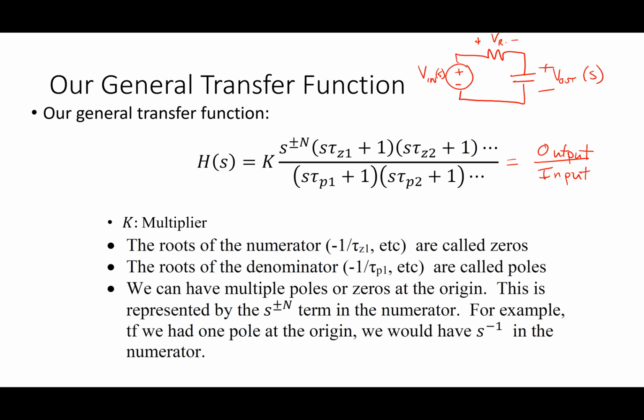Okay. So I already wrote here the question I'm going to ask you. We defined poles and zeros, right? What is a pole? It's the value of S that causes this thing to go to infinity. So when I look at this, in this particular case, I usually draw it out in this form where it's all factored. This is what I call my general form.